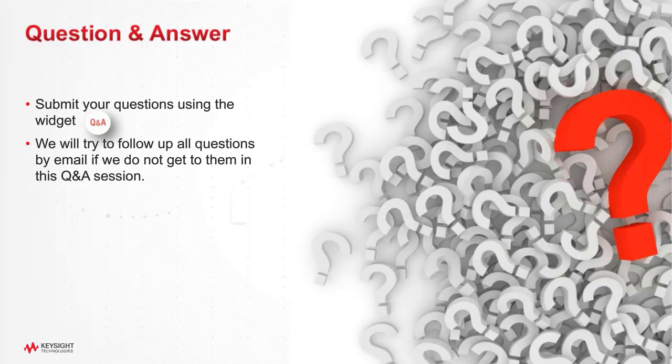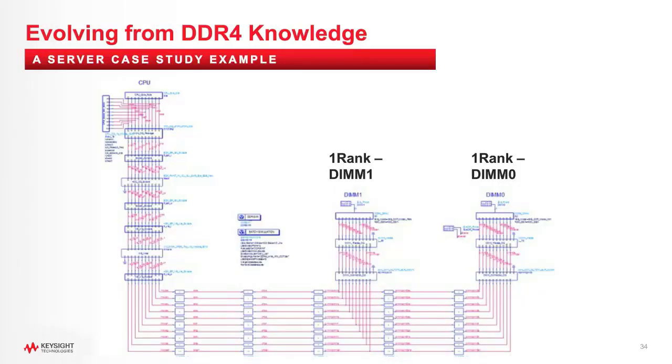Yeah, great. So what I might do is I'll just push us back to one slide to talk about that. So in this slide, this is actually a case of what we call pre-layout exploration. So you can see for each of those individual pieces, those blocks, they each have variables for things like width and spacing of the traces. But in fact, instead of doing a continuous sweep over all of those different variables, you have to break the simulation space down into smaller pieces.